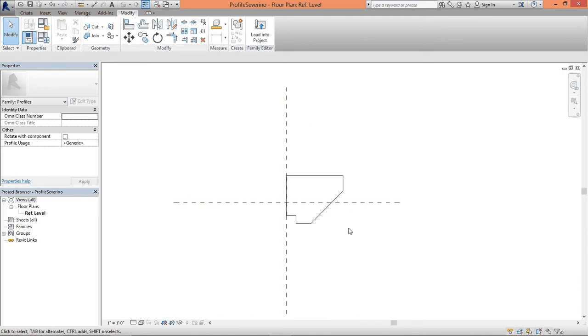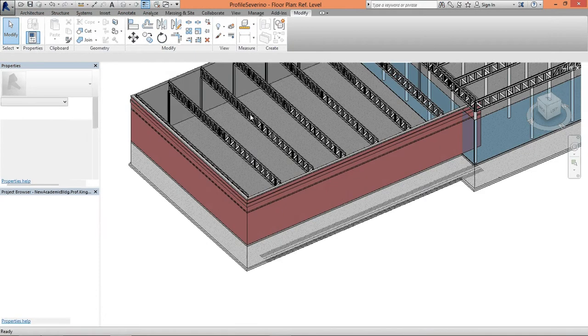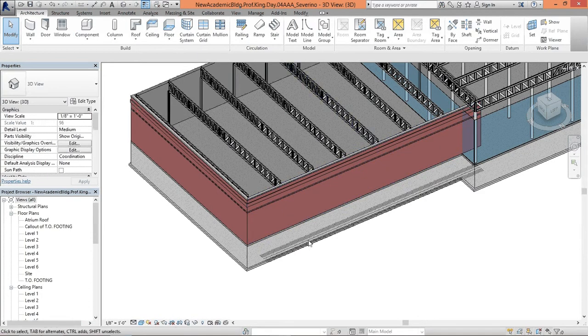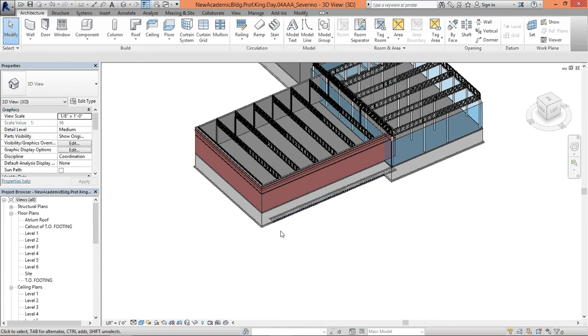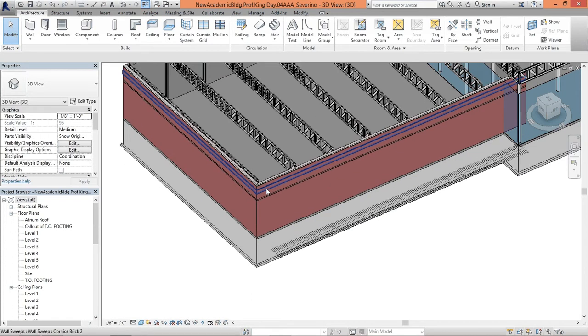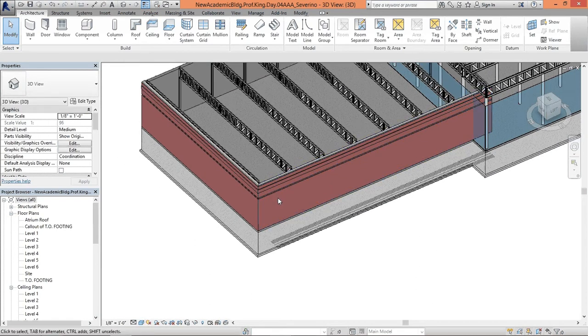And here's the step from a family. Again, it's not exactly a Revit file. It's a family aside from the Revit file. You have to load it into the project. If you only have this one project open, it will automatically load here. If not, it will ask you where you want to put it. So it's a good thing to know.